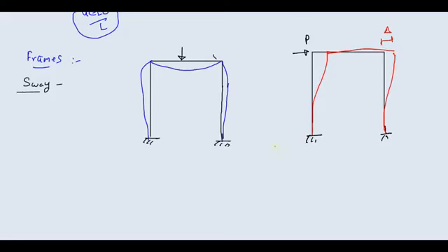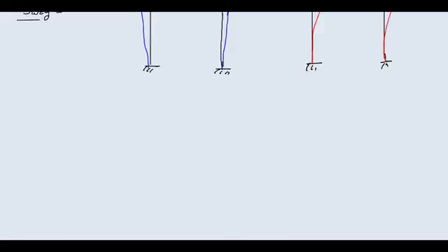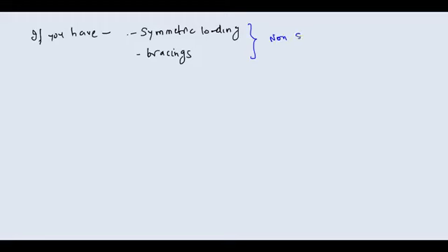Okay, so how will I judge whether my frame is going to sway or not? Because you have different analysis for sway frames and non-sway frames. If you have symmetric loading, or if you have bracings, in these two conditions you can say that you will have non-sway frames.